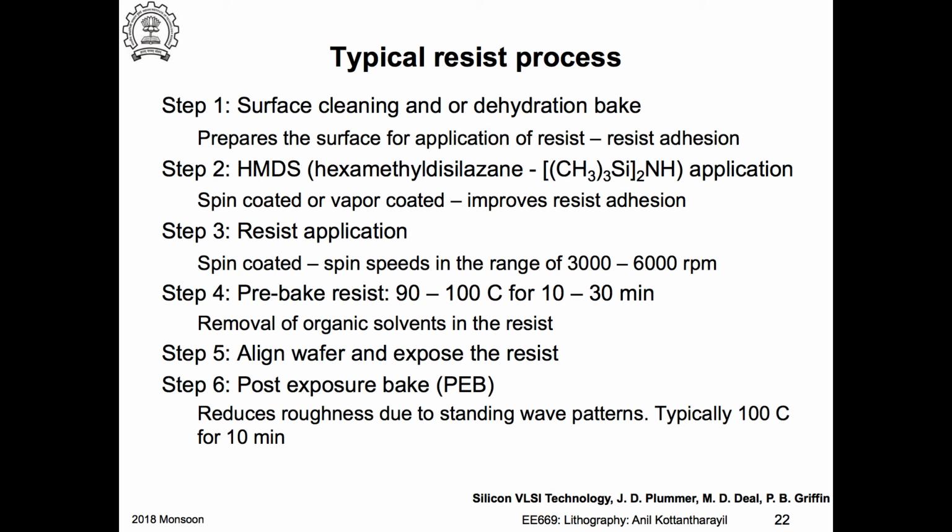This is the sulfuric acid hydrogen peroxide mixture, and this is quite aggressive. So why do you need to resort to different kinds of things? It may not be that isopropyl alcohol can be used for removing any photoresist. That is not possible, and the reason is that after your photolithography, you're going to use the photoresist as a mask. So whatever you're doing here may result in some changes in the properties of this material.